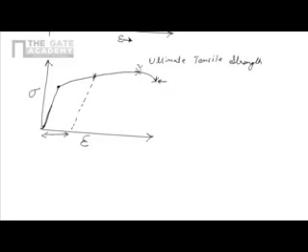This point is called the failure strain. In design, normally we use ultimate tensile strength. That is the normal consideration. We do not go to failure strength because we do not know what happens in this zone. We have no idea. This is a highly unstable zone.